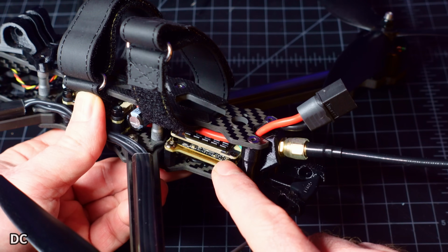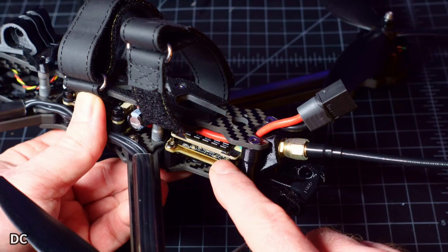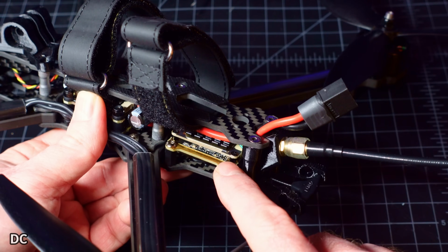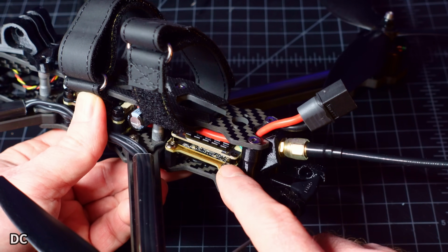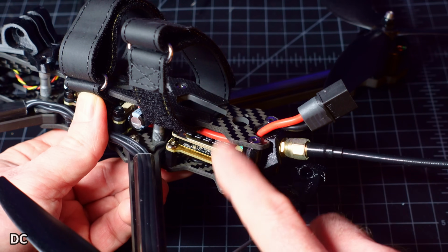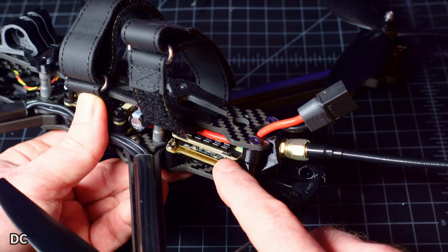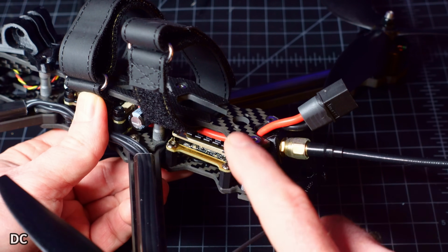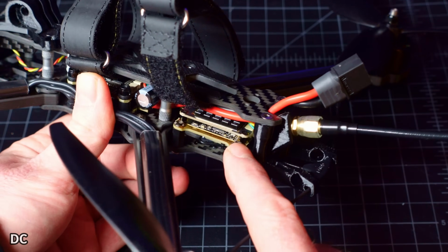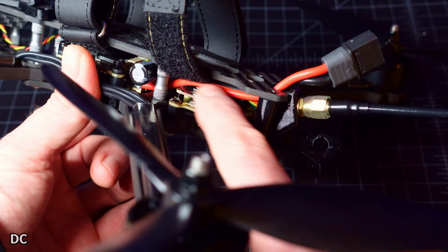It could be environmental, it could be something also RF in the air, maybe you're in an urban population, maybe there's Wi-Fi, there's tons of reasons, but a very simple reason that sometimes this happens is that this video signal wire coming off of the VTX is running too close to your power line.